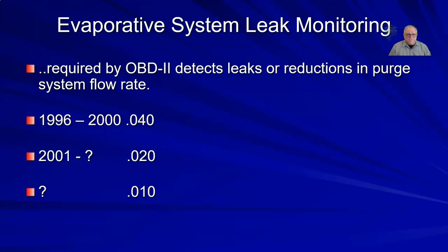When they put the PCV system on an engine, the hydrocarbon emissions that were in the crankcase, that we were using a draft tube to pull out and just send to the atmosphere, they started running back through the engine, and we reduced hydrocarbon emissions on the car by 20%. When they sealed up the fuel tank, we reduced hydrocarbon emissions off the vehicle by another 20%. This one is critical for reducing hydrocarbon emissions, which contribute to our photochemical smog.